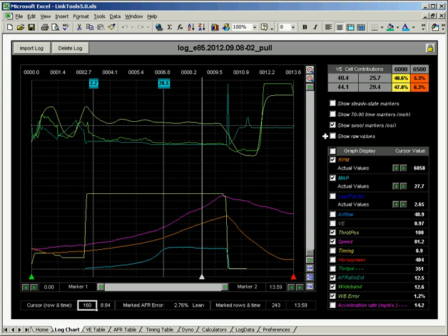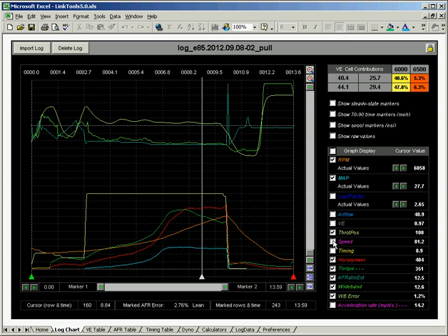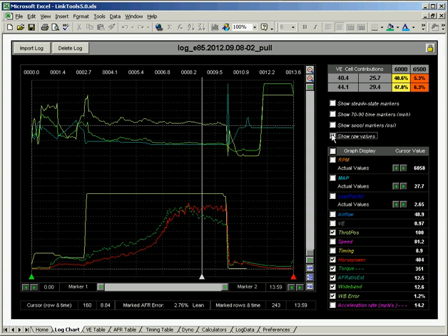And finally, we can look at raw values. For example, horsepower and torque within the program are smoothed. It performs some post-processing on them so that you get nice smooth signals. If you remember on the export video, we talked about how raw and choppy they were. If you look at raw values here, you can see the raw data compared to how LinkTools has smoothed them and created an average curve without actually shifting it to the right.